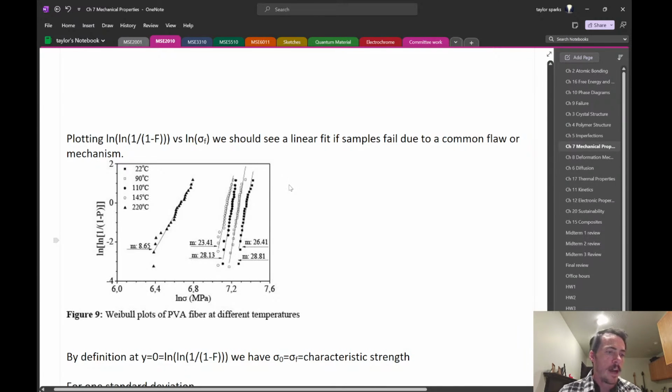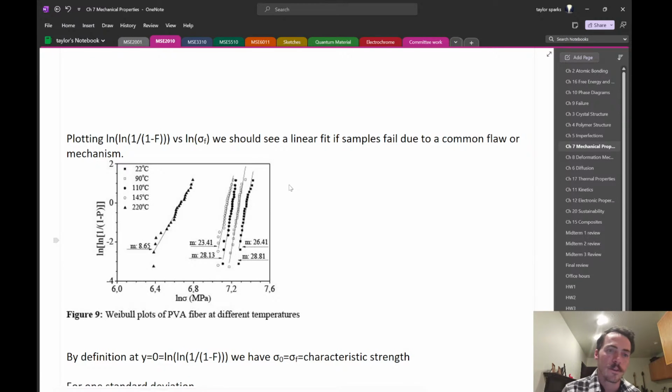So how do you do a typical problem like this? Well, there's lots of ways that we could ask questions about this. For example, I could provide this data. Maybe I provide data that's already been fitted, where I could provide a y equals mx plus b linear fit to that data. And then I could ask a question like, okay, given that Weibull fitting, you tell me for these test bars, what would be the stress that would cause 1,000 out of 1 million to fail?